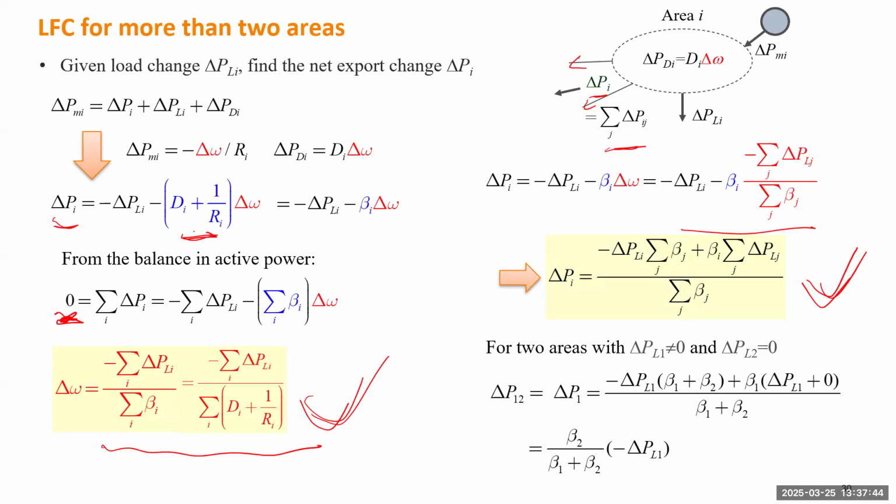All right, from those examples, we know when there's any load change in the system, eventually there will be some frequency deviation, which is given by this formula. If you have a bigger D or smaller R, or you have many generators, all the generators will have some droop control and will introduce some R, which is like a circuit with many parallel branches.